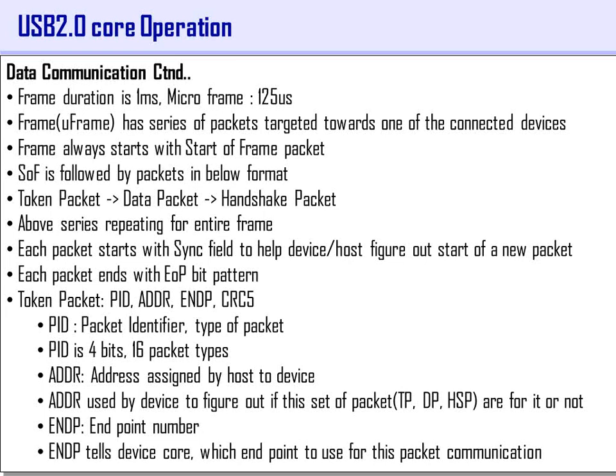So it will generate a token packet with what? Only endpoint number 3. Let's say it has to give the data. It can't generate endpoint number 3. So that is where device drivers come into the picture. They know all the information. They accordingly know whether I need to read or write, do I need to do isochronous or bulk? Accordingly, they will choose the right set of endpoints.